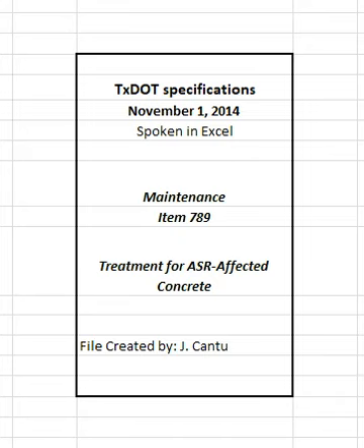Apply the SREP topcoat after the caulk has cured according to the caulk manufacturer's recommendations. Provide a smooth, uniform coating using a roller, brush, or airless sprayer. Back roll spray applications. Apply a first coat with a minimum wet film thickness, WFT, of 4 mils. Apply a second coat at least 24 hours after the first coat with a minimum WFT of 4 mils.